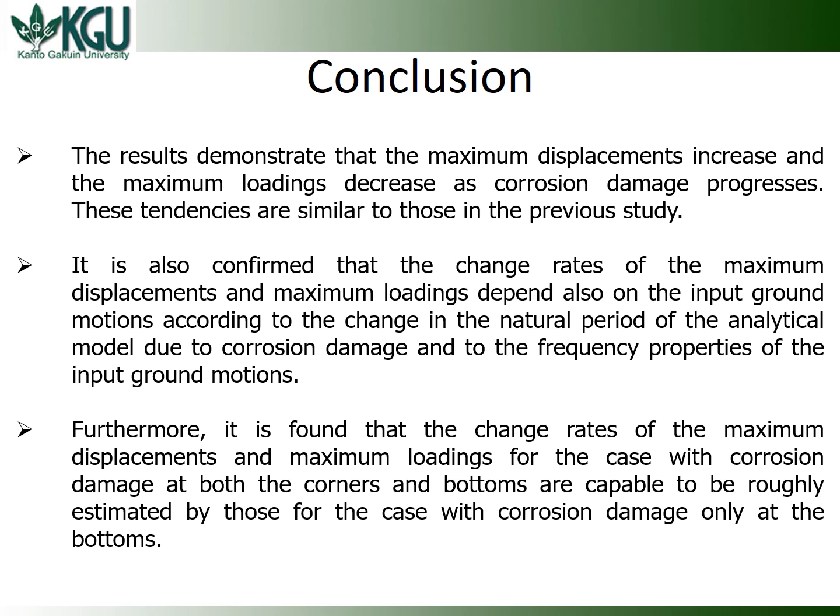Number 3. Furthermore, it is found that the change rates of the maximum displacements and maximum loadings for the case with corrosion damage at both the corners and bottoms can be roughly estimated by those for the case with corrosion damage only at the bottoms.